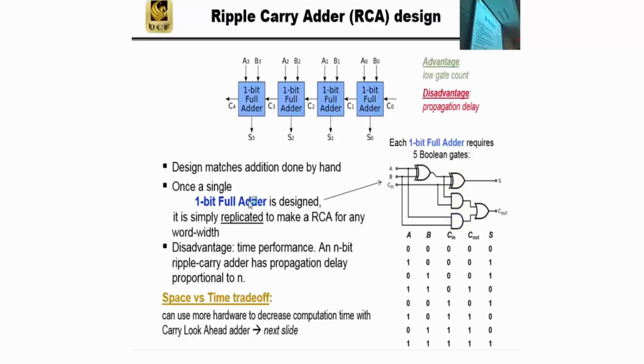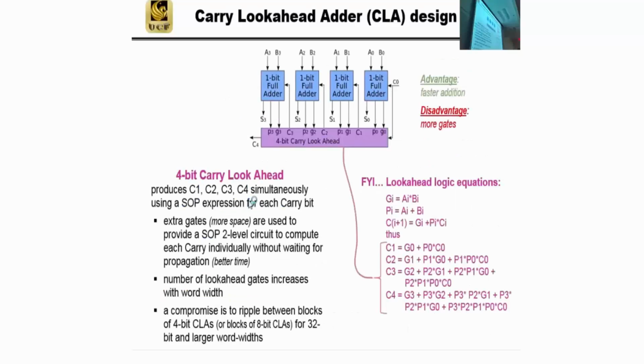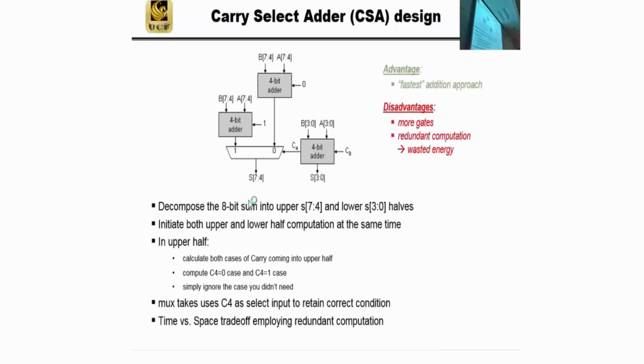This is way faster, 100 picoseconds faster than the carry look ahead, because it uses 2-level sum of products. What's the disadvantage? A lot more gates. Too many gates. If you have the area on the chip, you can put the gates there, but maybe it gets too hot. That's a trade-off. Kind of getting wide here, right? Too many inputs. That's where I said you can ripple between the blocks as a compromise. That's usually the most usual practical design. So here are the carries we just computed, 2 gate delays. We're going to give you a problem in a minute.